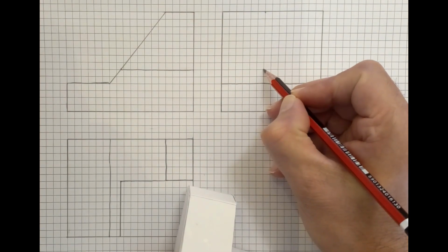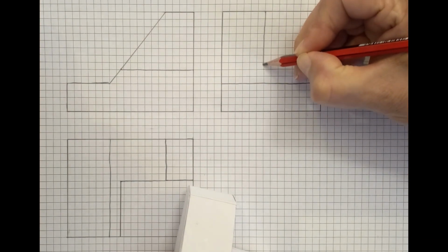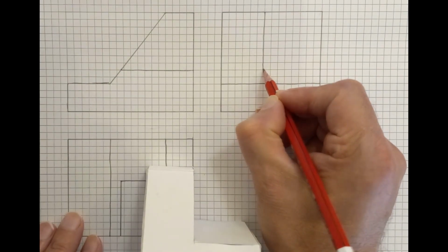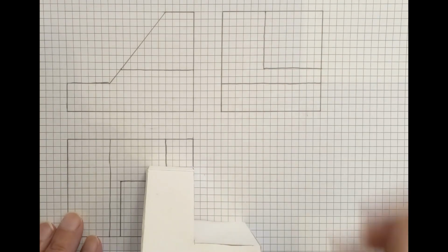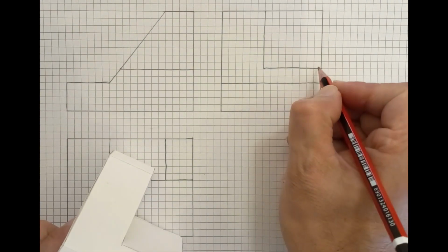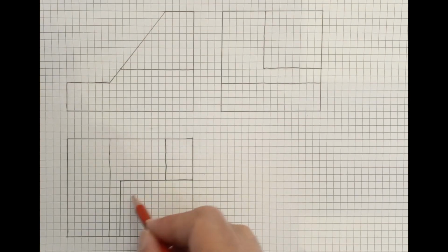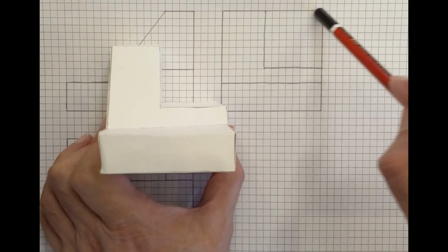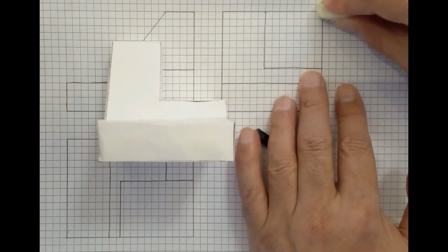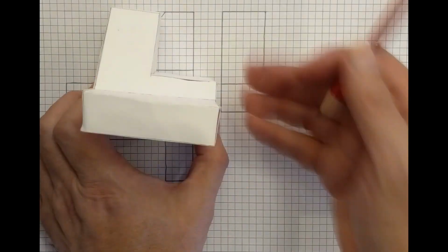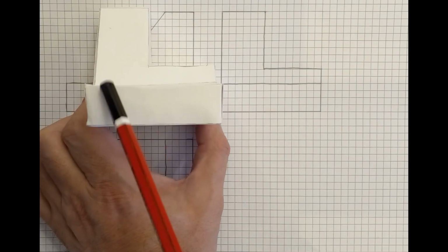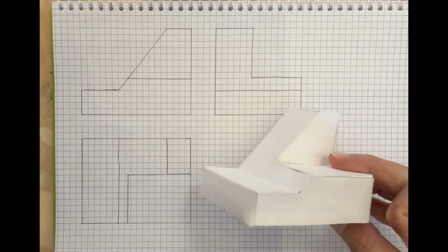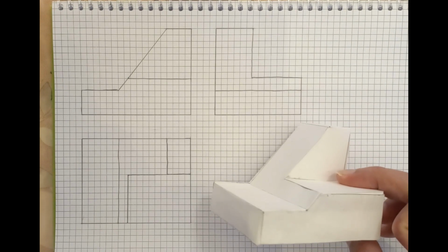So the end of this line is this point. And from this point I will draw another horizontal line like this. This edge and this edge represent this rectangle. Okay, we have a space here, so this means that we have to erase these 2 lines. So review again. We have here this rectangle and this L shape and the space. Now I finished the 3 views of this part.